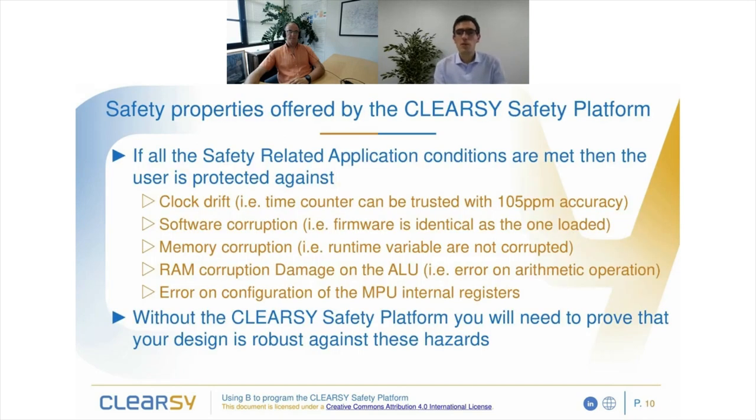When you meet all the safety properties, the safety-related application conditions of the CLEARSY Safety Platform, you will benefit directly from the certificate, and you don't have to handle a lot of things. So you have some guarantees that are offered by the platform. They are listed here. You have a guarantee against clock drift, so you have a time counter that you can trust with a 10^-5 accuracy.